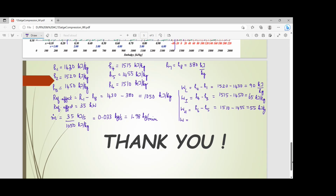So total work done is WL plus WI plus WH, which is 90 plus 65 plus 55. How much is that? 55 plus 65 plus 90. That's 210. So you can multiply this with the mass flow rate and get the power, but for COP, I'm not going to do that. If you want, you can do that.